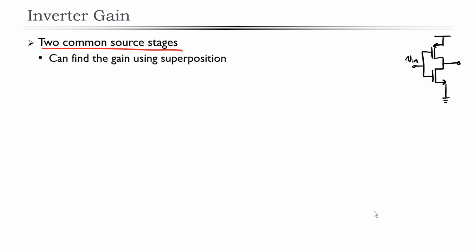So it's nice and great that we managed to measure the gain of this amplifier using two different methods, the Keithley source meters as well as the oscilloscope method. But what is ultimately important is to be able to derive an equation that represents the small signal gain of this amplifier based on device parameters. That's ultimately what you want to do in order to be able to do some analytical work on this when you're designing circuits later on. So how do we do this?